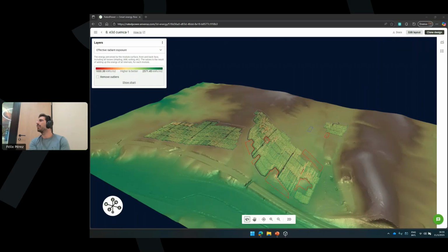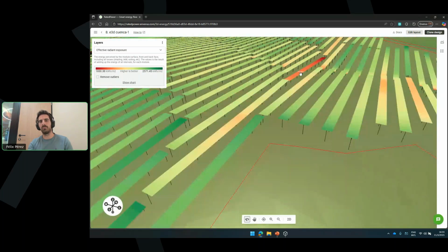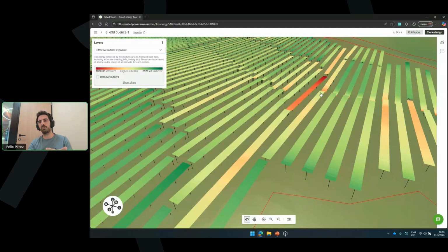So we have the backtracking algorithm. Is the backtracking algorithm related to the tracker selected, which SAT informs the terrain tracking option? Right. The backtracking algorithm is done tracker to tracker. Essentially, we look at one individual tracker in the PV plant, and we compare the position of this tracker to its neighbors, and we calculate the slope-corrected backtracking angle with that, right? So it's always individual per tracker, considering its neighbors.